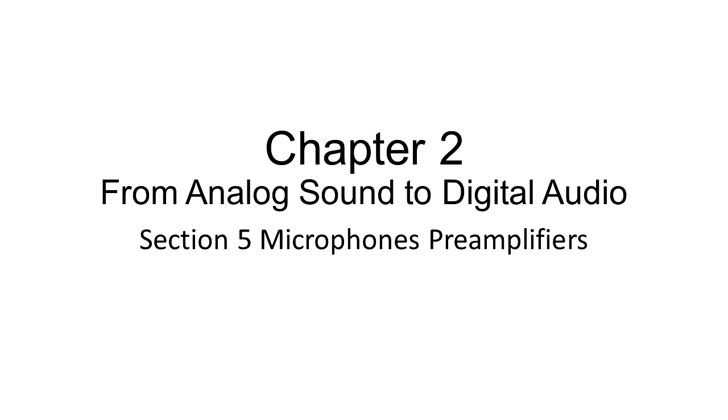How these devices amplify the signal is important, since we know that any electronic component put in the electrical flow will alter the original signal. How does a preamp work? A preamp consists of a chain of electronic components. First, the input, usually a balanced male XLR input, since that is what microphones usually use as output.